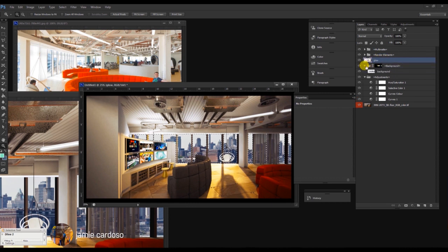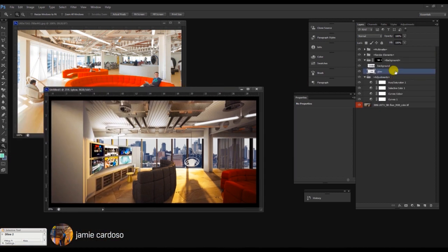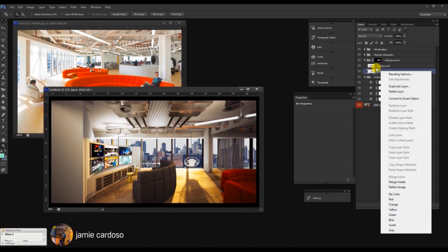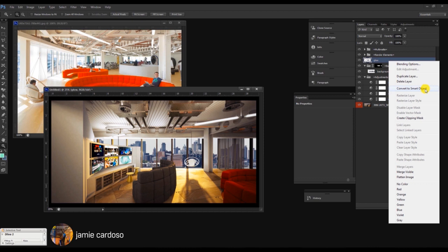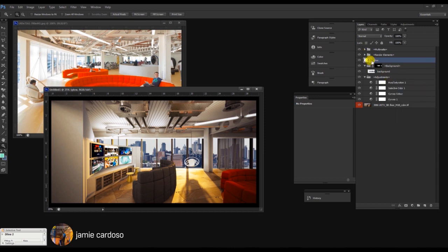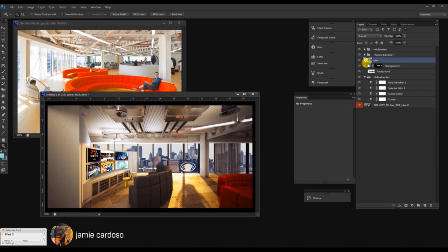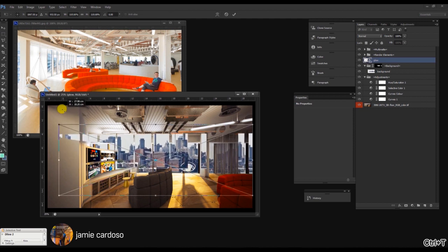Yeah, we're going to leave that glow there. The reason being is because if you move that glow into there, it's just going to be restricted to the mask, but we want the glow to be seeping through the windows. So what we're going to do is to convert this glow layer into a smart layer. The reason why I've done this is because you want that particular layer to retain every single effect you apply to it. Also, even if you increase or decrease the layer, you won't change its quality.